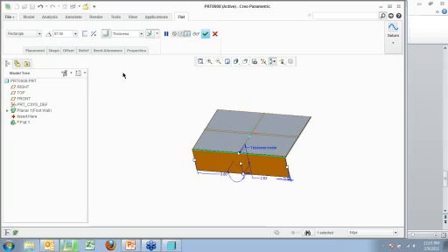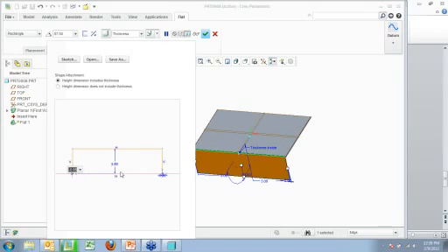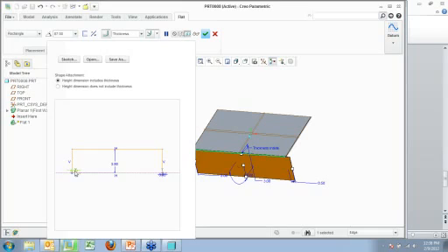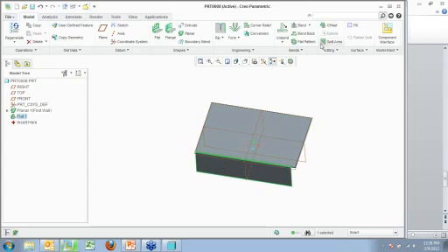I mean, the sheet metal portion of the update class is one of the larger portions. So I'm not going to do this justice by trying to cram it into 10 or 15 minutes. There's a lot of really cool things I've done with this, and some of this functionality was in Wildfire 5, but now I can go in and edit things directly. And say I want this to be, oh, sorry, that's the wrong way. Minus 0.5. I want that to be half an inch in from the end, half an inch in from the end. Turn off my planes.